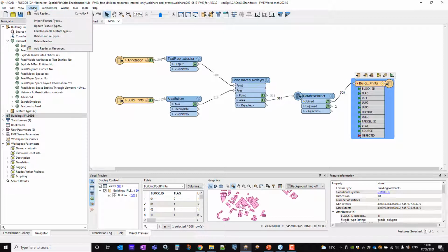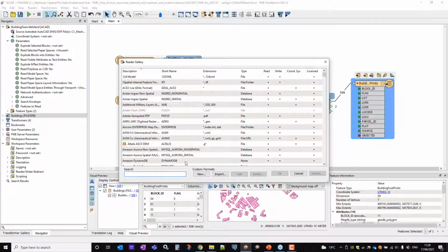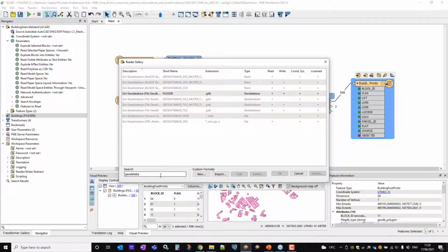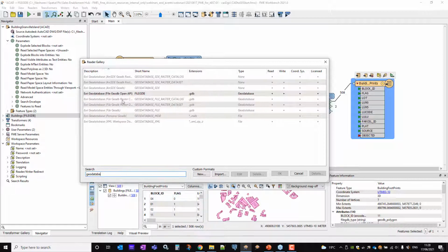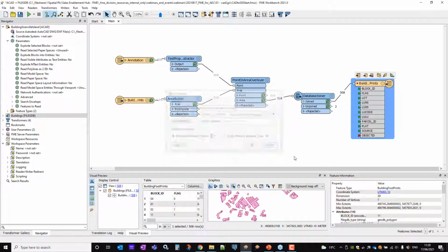You certainly can. There are a number of different format readers that you can select. If you want to get data out of a specific feature class, you can choose a geodatabase reader just on the geodatabase format itself. There is a free and open source reader and writer in FME, but there is also an official one. This requires you to have some Esri software installed on your machine, but if you do, then you can use the more feature-rich way of reading and writing geodatabases. So reading and writing geodatabases is possible. You can also insert, update, and delete into particular feature classes.